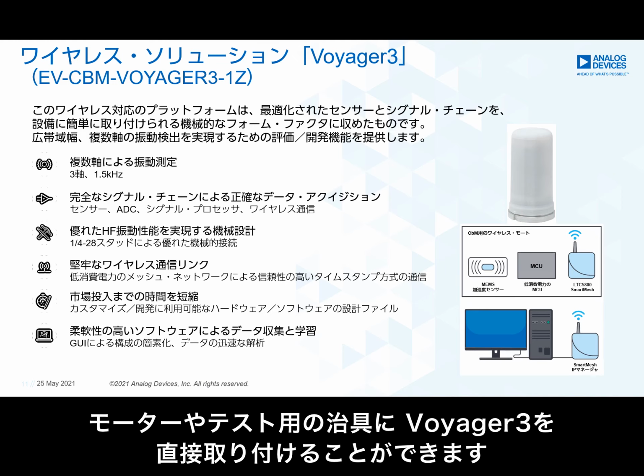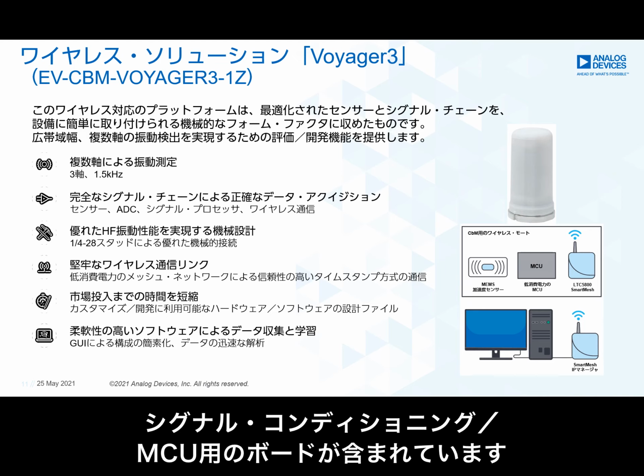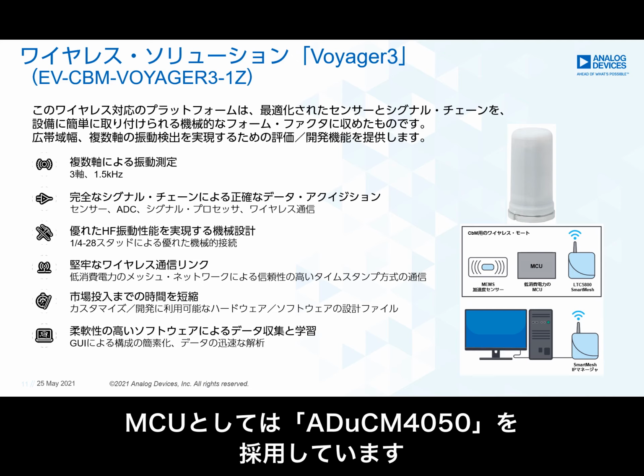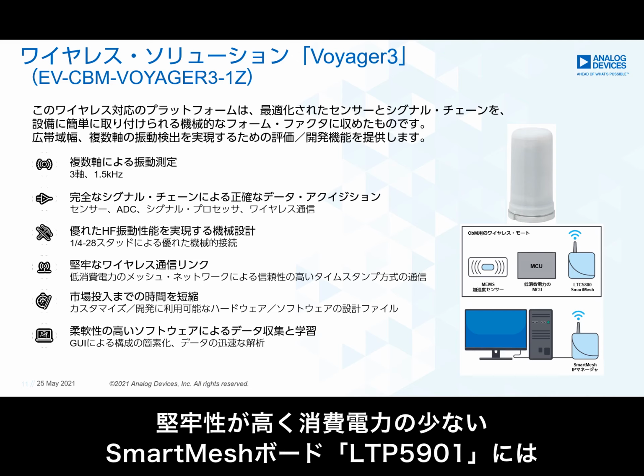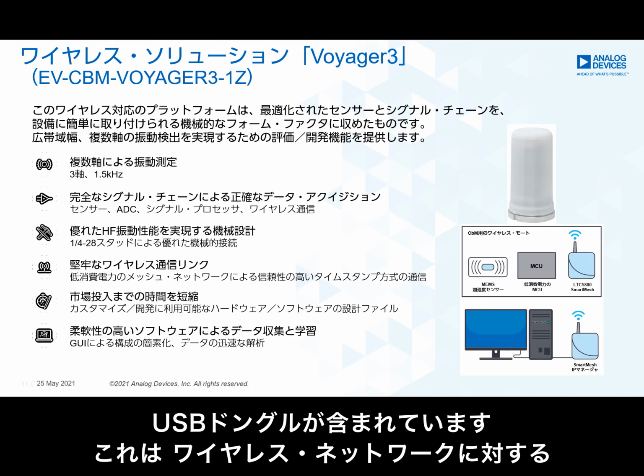The mode also includes a 3-axis 1.5 kHz ADXL356 vibration sensor board, as well as signal conditioning and microcontroller board using the ADuCM4050 microcontroller. A robust low-power SmartMesh LTP5901 board is included with chip antenna. The kit includes a SmartMesh USB dongle, which serves as a network manager for the wireless network.